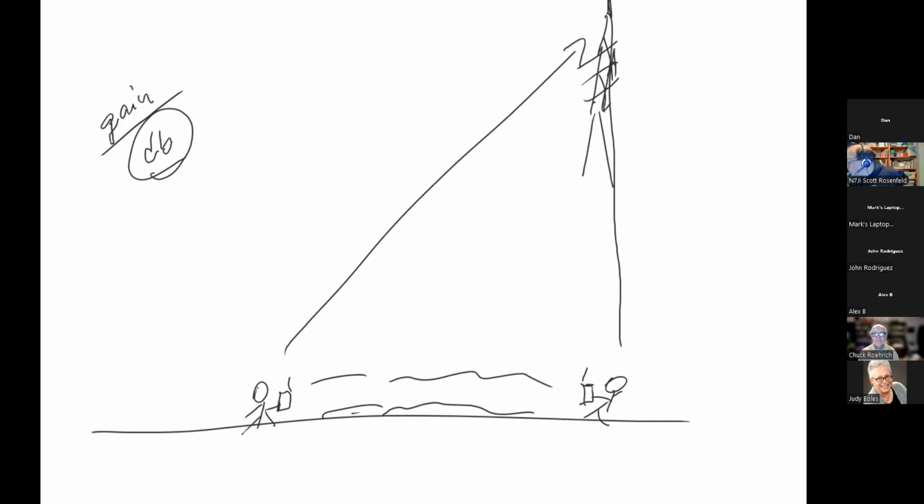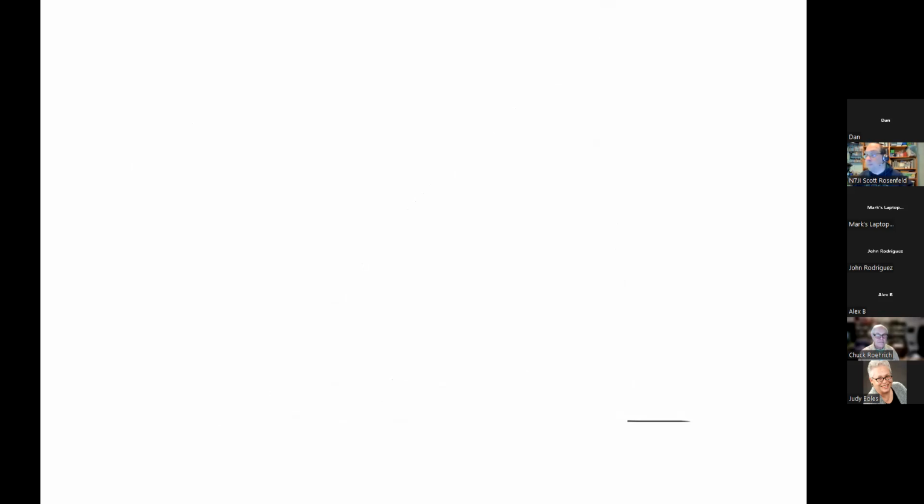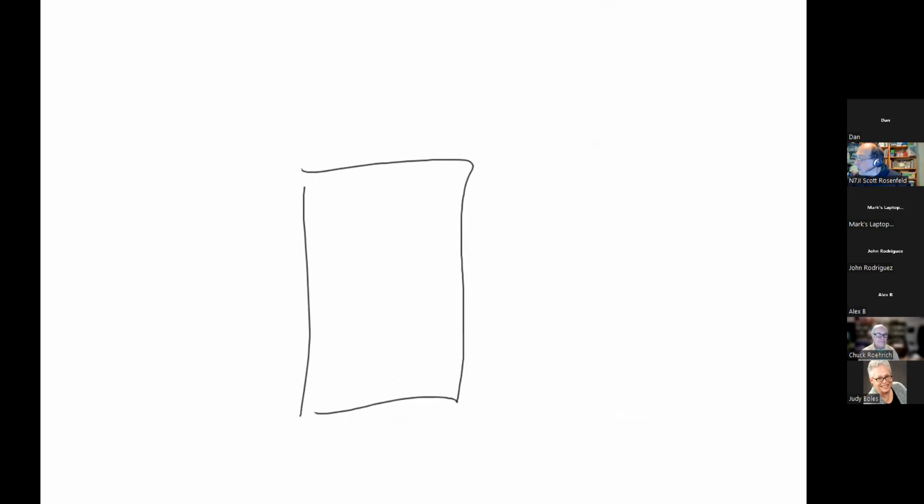Now, there was also another company that made something called, believe it or not, a stubby duck. So here's your radio, and here was the antenna. This is a 2-meter antenna, and this is real size. It was 1 inch long. How long should it be electrically? For a quarter wave antenna? It should be 19 inches. It was a 1 inch long stubby duck antenna.